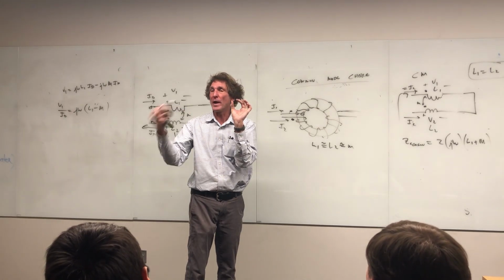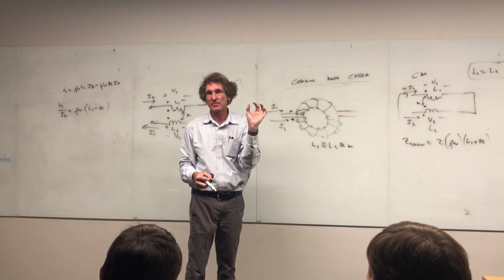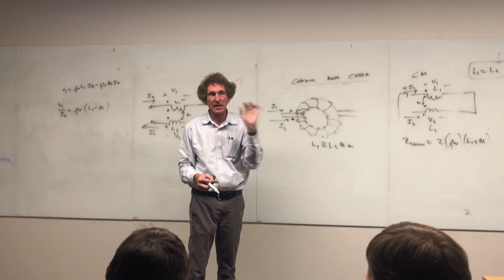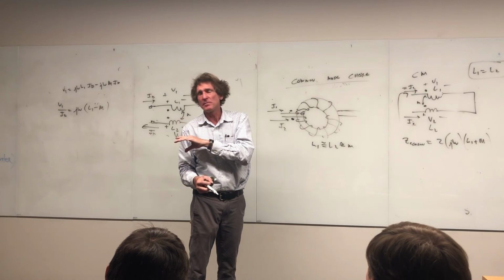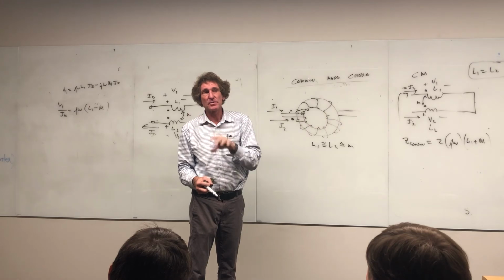Now actually you want to go way beyond that, to tell you the truth. You want maybe 10 times that because you don't want a chance of arc overs. But that's what you have to deal with in the real world if you're dealing with common mode currents caused by lightning. Remember that common mode currents can be caused by other things. They're called ground loops and stuff we'll get into. But lightning is the troubling one.